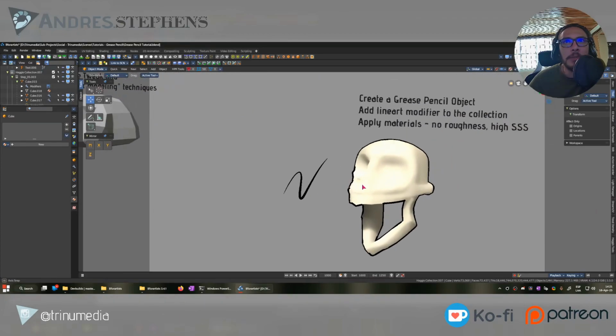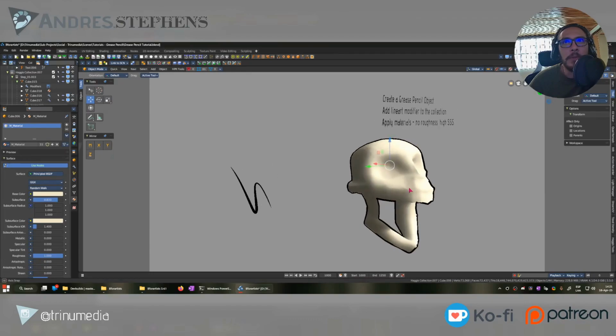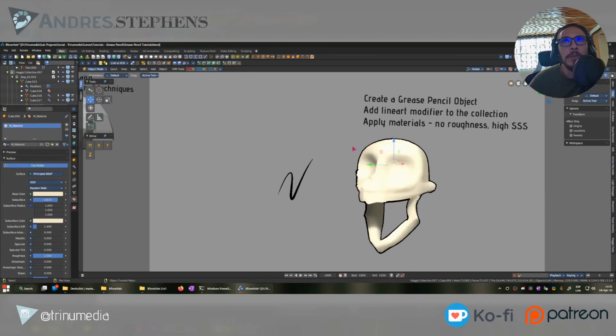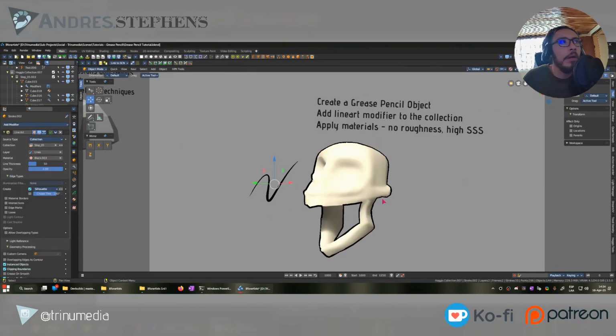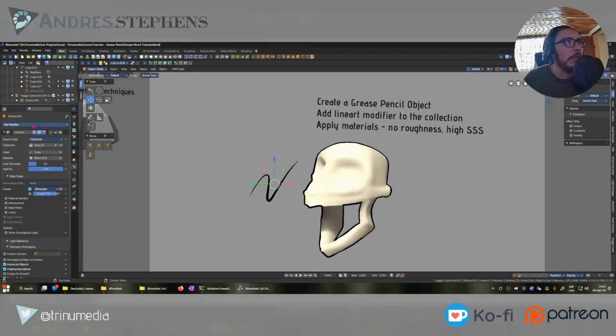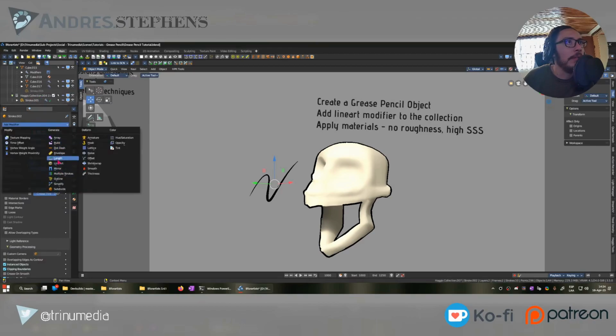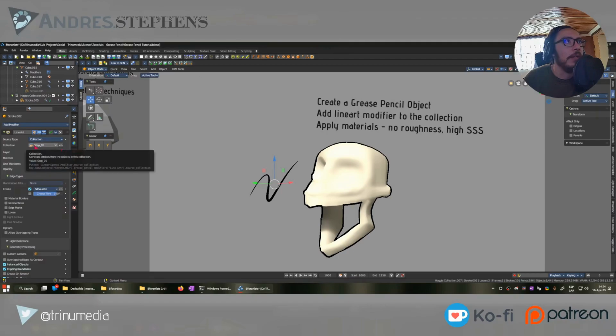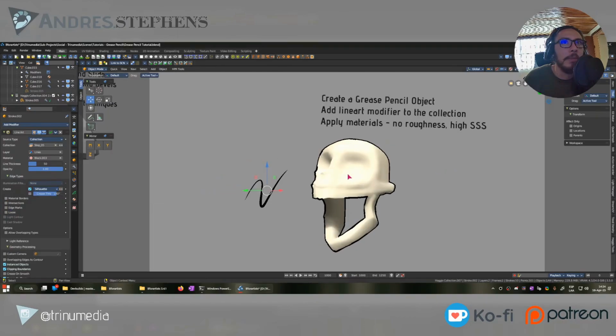To get the general shape of an outline that's dynamic to the 3D view, we can use the grease pencil Lineart modifier. From there, we add a Lineart modifier to the grease pencil that we have created. This Lineart modifier will help us to define a silhouette for the collection. So we need to make sure that the edge types and everything are turned off, or else it'll look a bit janky. And make sure that we create only a silhouette. And then we're good to go.